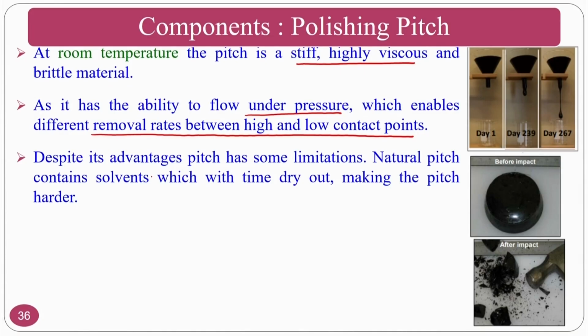Despite the advantages, there are also some limitations. Some of the natural pitches contain solvent which may dry out with respect to time, because the temperature will increase. If the temperature increases, the solvents will go off, and then the pitch will become more stiff. So the material removal rate will be very high and the roughness will increase. That means that nano polishing you may not get.